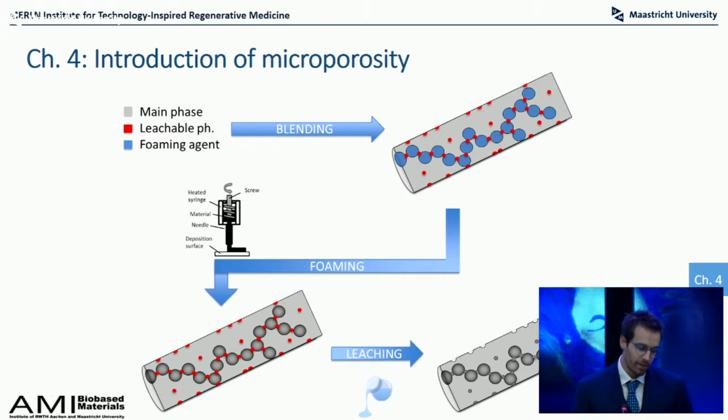So briefly, after mixing all these materials, during printing of the scaffolds, upon the application of heat, the baking soda would just form all the pores you see inside cakes and inside our scaffolds as well. Eventually, after incubation in water, the water leachable phase would just be released from our scaffold, allowing the interconnection of the pores internal to our fibers, but also the opening of these pores to the outside, so effectively creating an interconnected network that is also open and accessible from the outside.